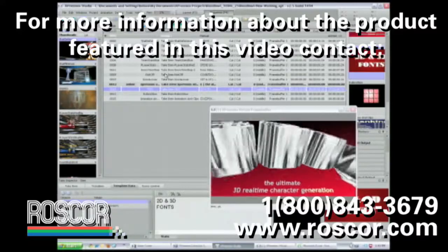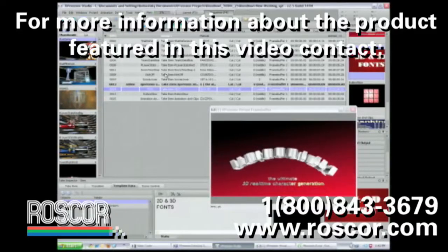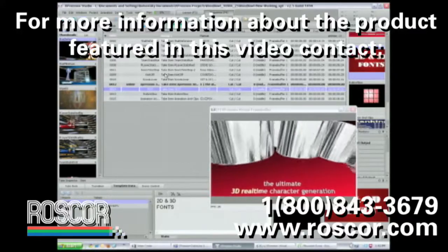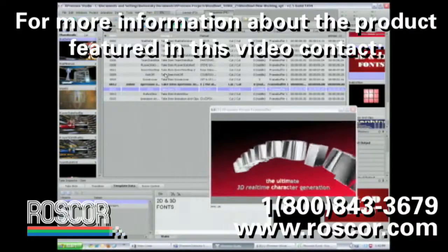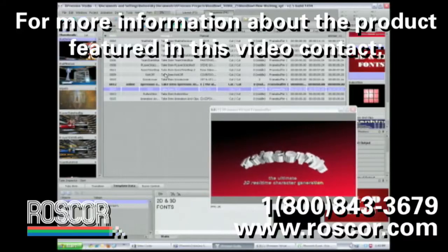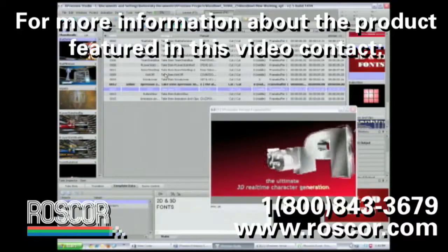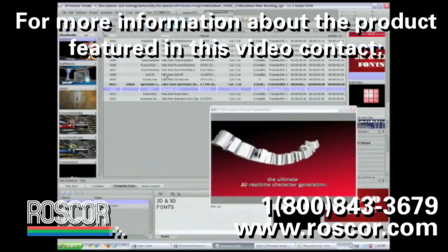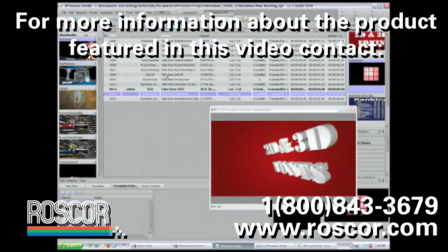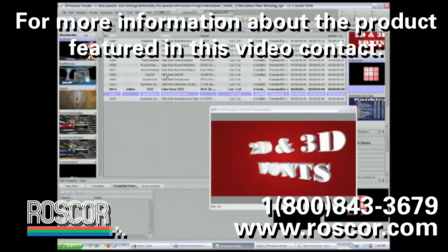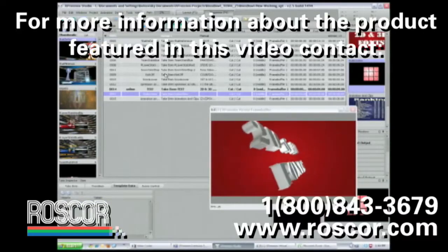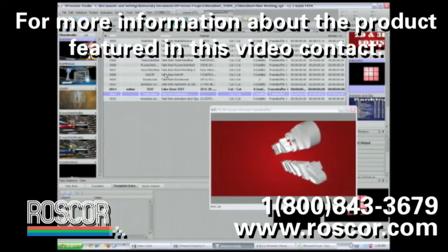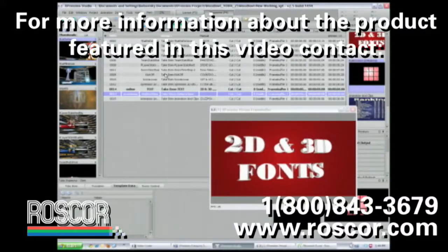This particular animation takes advantage of the continuous animations we can do inside Xpression. We're just rotating on multiple axes and moving the Xpression logo forward and backwards in Z-space. You can also see a little bit of a lighting effect. We've got a yellow spotlight running across the text below. 2D and 3D fonts, any TrueType, OpenType, or Adobe Type 1 font can be used in either 2D or 3D within Xpression. There's no need to have any special type of font.